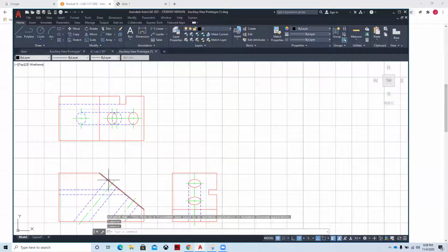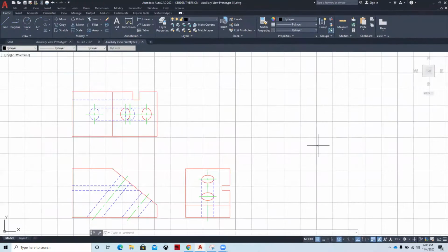Then you'll project the auxiliary view off of this edge view into this area, because from what I noticed, we don't have the dimensions for the top, front, and right side view. Also, by the way, Joe, what is it, 45-degree angle we cut that at? So we drop the lines from that front view to the third dimensional view outside on a 45-degree plane. Yeah, usually what I'll do is I'll just offset this at some point out here. And we do have a really good video on it, so I don't want to go too far into it because we've already got that covered.